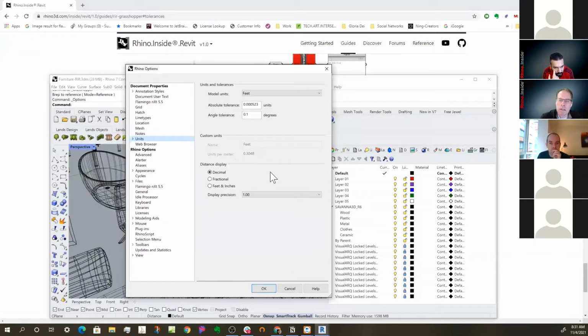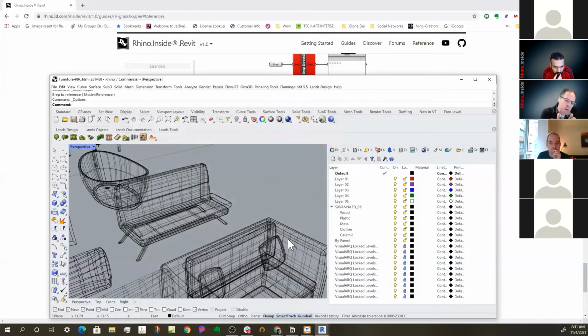But what I wanted to talk about is some other interesting ways to do this. The way Rhino to Revit works is that initially we take the Rhino geometry raw in the NURBS form, and we use an API call to try to recreate those NURBS BREPs in Revit. There's a way to do that through the API. And if that works, we're in great shape. And it's fast, really fast.